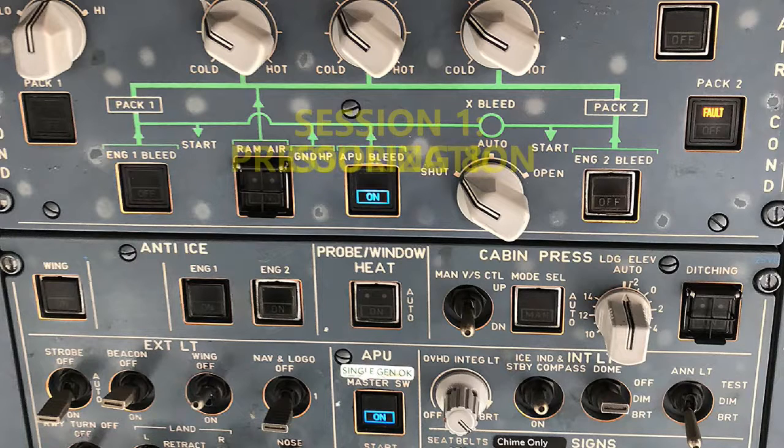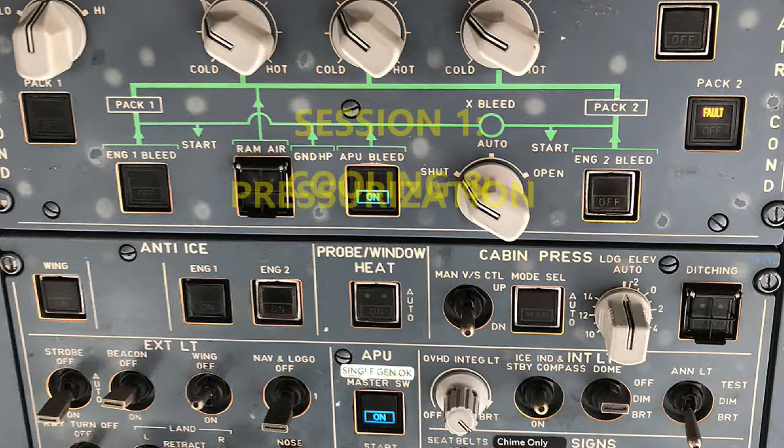There's also a ram air push button switch that, when you push it, opens up the emergency ram air inlet. Remember I said about the color, that might be a test question, hint, hint. There's a guard on it, so you have to lift the guard and then depress the push button. Then a light will come on, whereas in the other cases, if you depress it, there is no light. The ram air push button has its own light. When you push it in, it's a blue color, and that's what opens up the emergency ram air inlet.